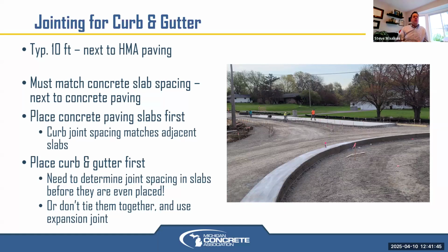And then if you are doing concrete, in this case, you see this is probably a roundabout. I think, yeah, this is a roundabout approach. You can see in the background of that photo, they've already formed the inner ring of the roundabout. This I think was a full concrete roundabout. The problem with doing the curb first is you have to know if you're going to tie it, especially, but even if not, it's going to have some friction against each other, some keying into each other potentially.